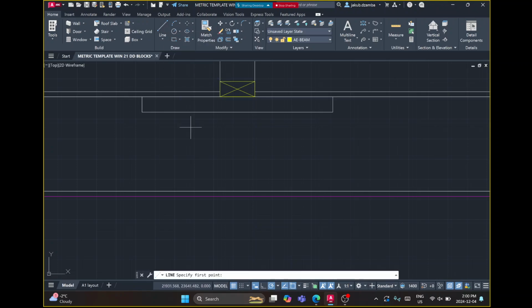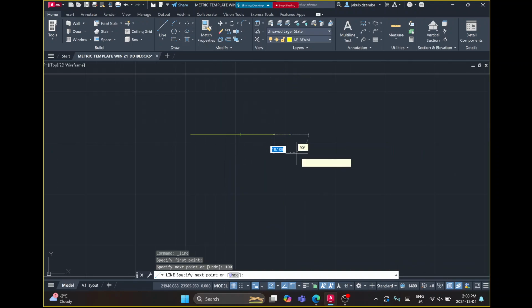So what I'm going to do is, first I'm just going to draw it, and I'll move it in place after. I'm going to go 100 millimeters this way. Then I'm going to go 10 millimeters down, because I'm going to guess the steel is 10 millimeters thick. Now it's going to have a 10 millimeter flange going down the middle, so I have to divide 90. It's 100 minus 10, which is 90. 90 divided by 2 is 45. So I'm going to go back 45, like so.